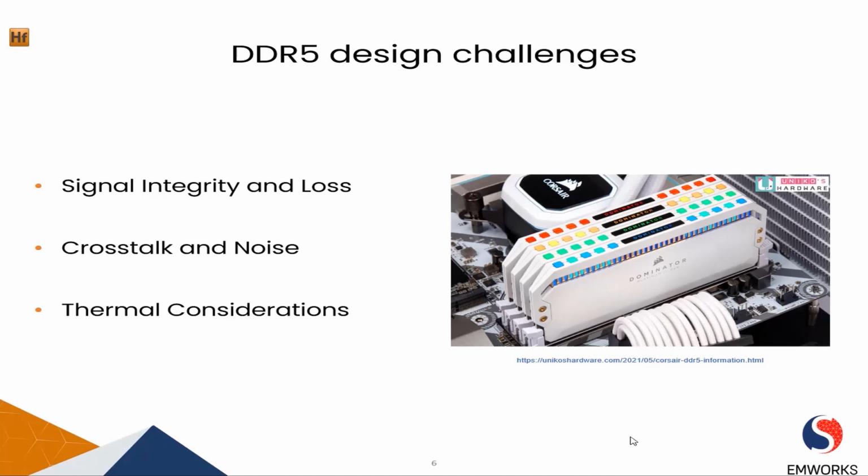As data rates increase, the effects of signal loss due to trace impedance mismatch, dielectric losses, and skin effect become more pronounced. Maintaining controlled impedance traces and minimizing losses become crucial to prevent signal degradation and ensure reliable communication between the memory modules and the controller.